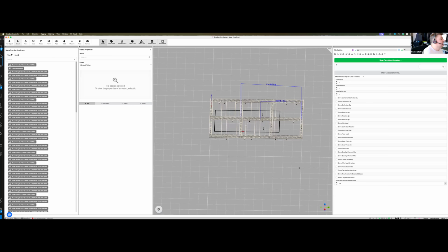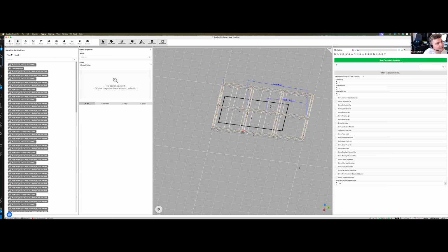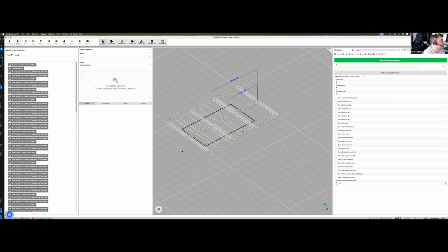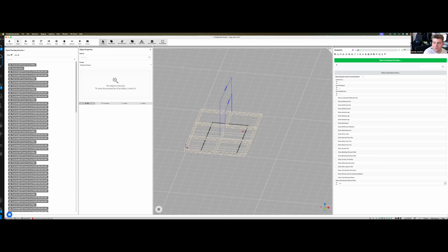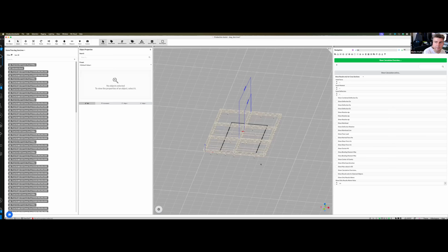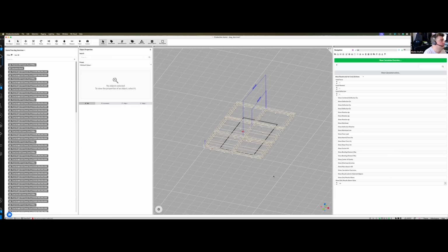This is actually a rig that has been calculated by our engineering office. The problem was that the roof capacity is rather small. For this specific rig, the roof capacity was 100 kilonewton. So the challenge was not to hang this, but to hang it and stay within the limit of 100 kilonewton. It took us a tremendous amount of time to find the correct places for the hoists so that we don't exceed this.